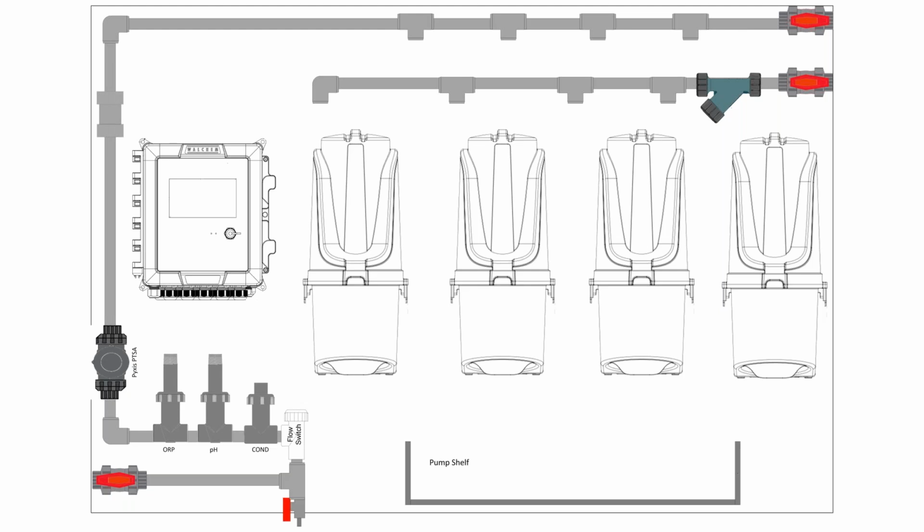The other thing, Tom, on these panel mounts for you guys is the flexibility. This shows a 4-product program. That's probably your extreme, right? It could be a boiler, this is cooling tower, but boiler chemistries might go to 4 products, or you might have a more stressed cooling water application where you need dispersant, non-ox, ox, and scale and corrosion inhibitor. But you can go single, double, triple. There's a lot of flexibility there.